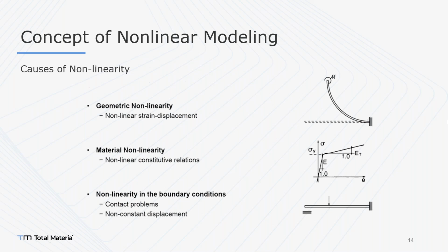Contact problems with friction will induce really highly nonlinear simulations. You can model at some point as linear, but after some displacement values, everything goes nonlinear, I would say. Basically, we have 3 types of nonlinearity we can consider: geometry, material, and contact.